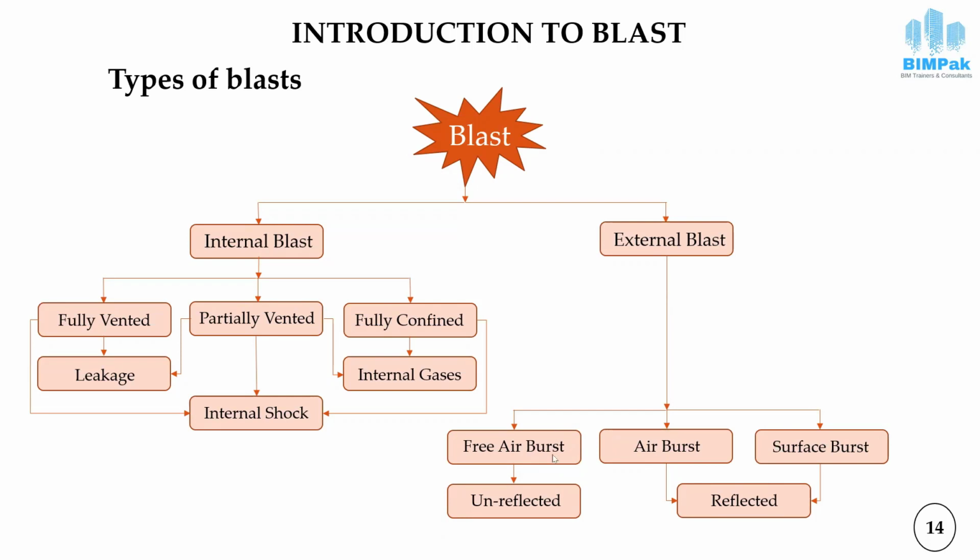In case of free air burst, an unreflected shock wave will be generated, whereas in case of air burst, a reflected shock wave will be generated, in both the cases, air burst and surface burst. As we have already studied in the previous slide, the intensity of the reflected shock wave is almost double that of the unreflected shock wave.